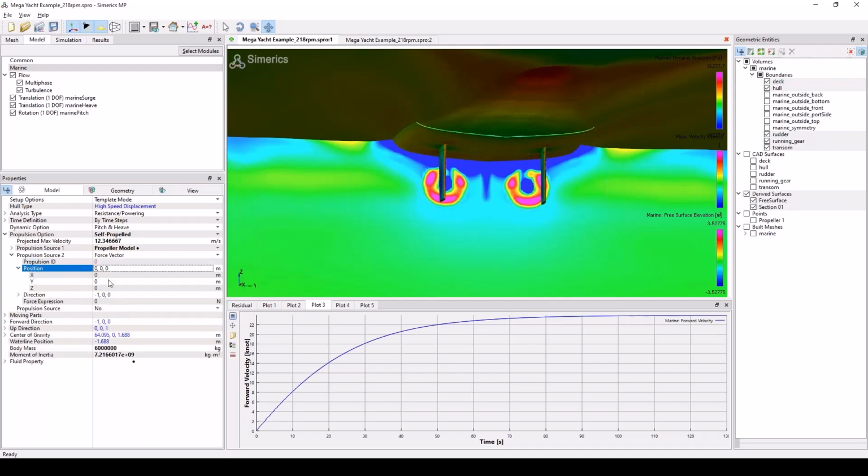It gives me a position. So you would place the location, the X, Y, and Z coordinates of that thrust vector at the back end where the water jet nozzle is, right? So wherever it was in your model, you'd put the X, Y, and Z numbers of that. The direction is defaulting to pointing directly forward, but if the water jet nozzle was pointing slightly up or slightly down or left or right, you would adjust the components of this direction vector. But then the last piece of input is the actual force from the water jet, the actual force of the force vector. It defaults to 0. So how do you get the water jet force in there?